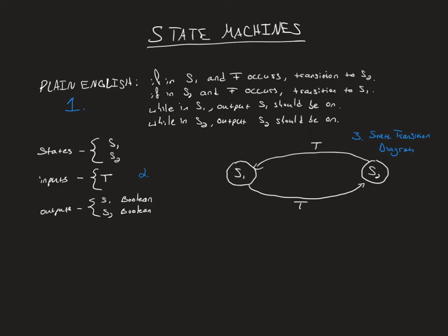Well, the easiest way to go about that, to actually make sure that you can only be in one state at a time and that you can only take on certain values, is to develop our own UDT. But that's a bridge, I think, a little too far. It's unnecessary. So rather than doing that, what we're going to do is define a tag that is an integer. So, right, we're going to have a tag called state, and it's an int, and S1 is going to be equal to the number 1.